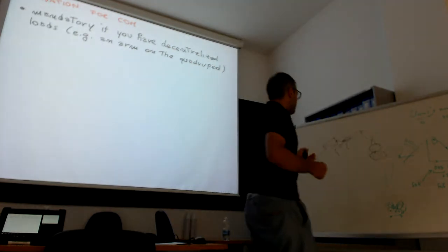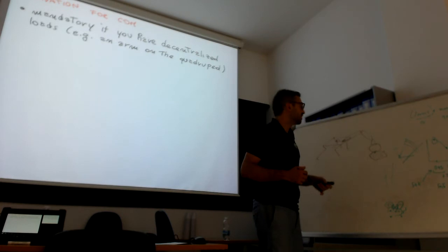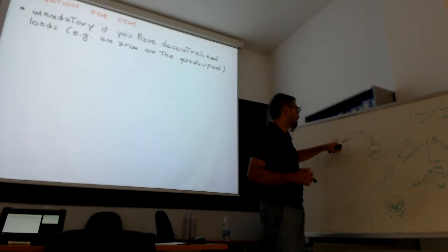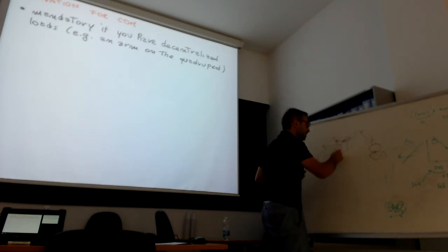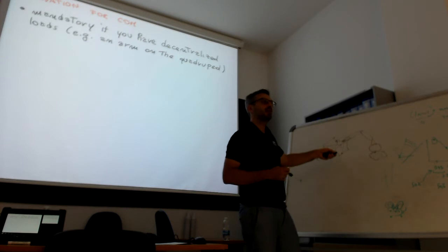Ideally, you can control the base, but the stability is related to the center of mass. So you don't care about moving the base point, you care about moving the center of mass point inside the polygon. So here the center of mass is very close to the polygon boundary and has very little robustness, even though the base seems in the middle, right?